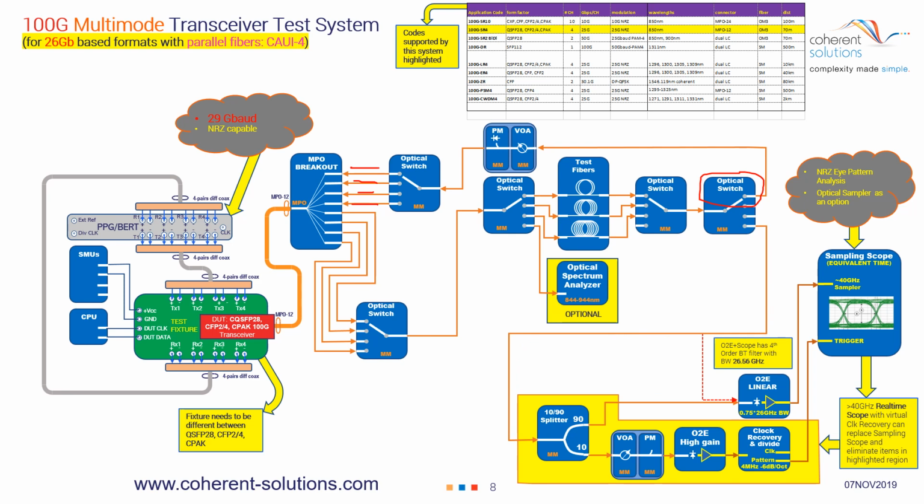Equivalent time scopes, which is what I'm showing here, require a trigger in order to look at the optical waveform. This is as opposed to a real-time oscilloscope, such as from Tektronix or Keysight Industries or LeCroy. In the case of an equivalent time sampling scope, such as a Tektronix CSA 8300, the scope does require a trigger.